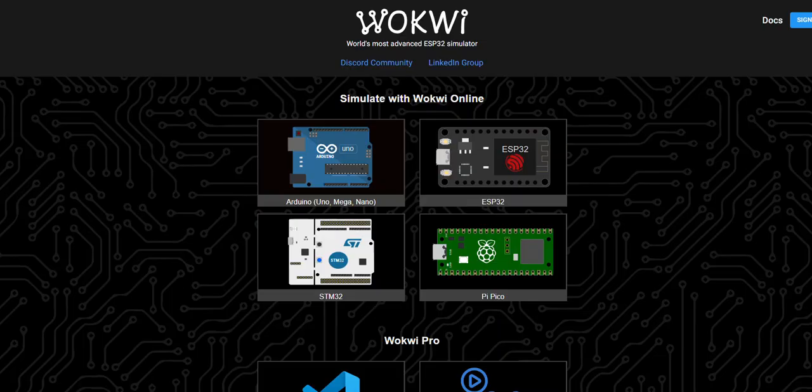So there's a common pattern. In the loop function, you read a sensor value using analogRead or digitalRead. You compare it to the threshold, then you decide whether to activate an actuator using digitalWrite. You might also use libraries to interface with more complex sensors or network devices, such as WiFi.h or SoftwareSerial.h.